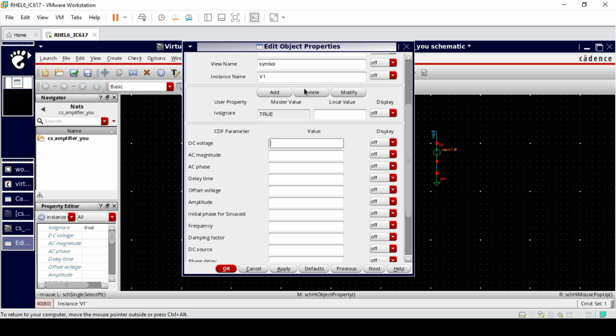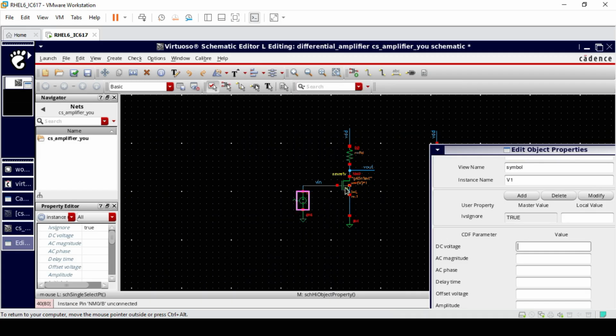Otherwise the transistor, as we are discussing, may go into the linear or saturation region, but the main criterion is to bring it out of cutoff. For that, a channel has to be formed, and for that a sufficient gate voltage needs to be provided. So there is an AC plus DC amount of voltage that we have to provide.